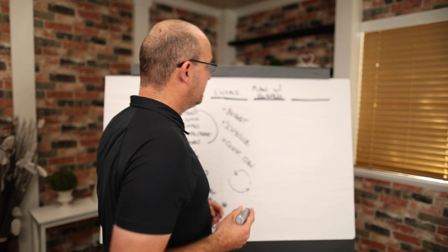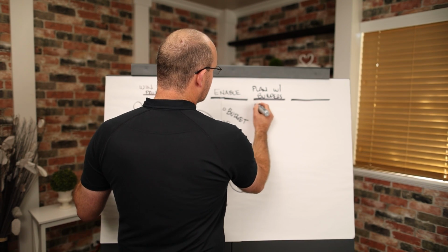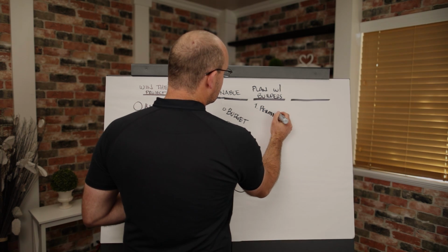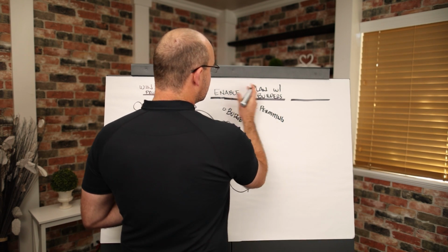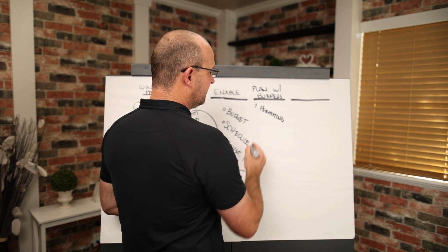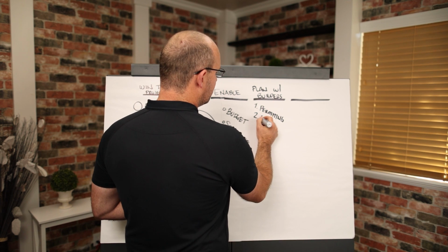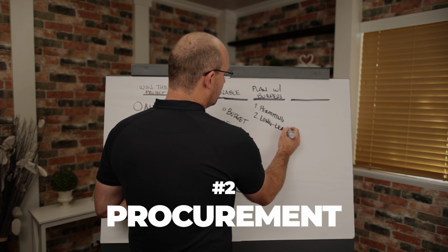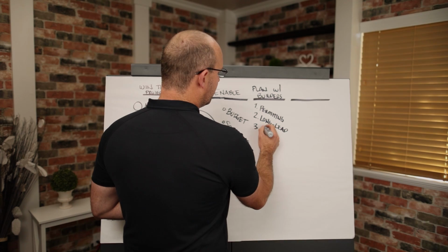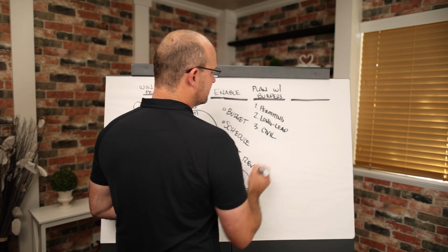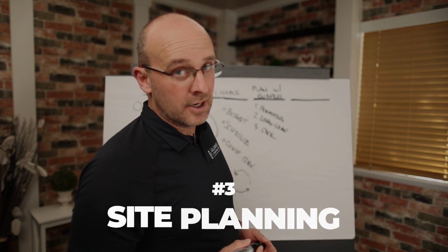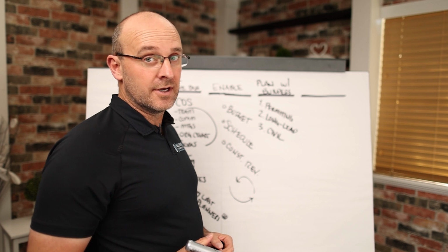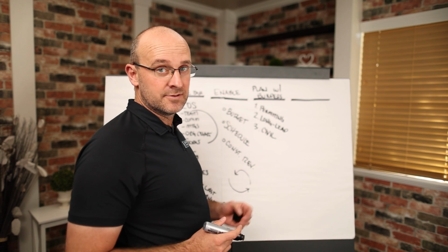So there's a couple of key things that we'll do in this phase. We will really lock down permitting, okay? And this right here can be in the design development CD phase. We are really going to make sure that our long lead procurement is well underway. We're going to make sure that any civil considerations like preparation according to the soils report or any relocation of underground utilities is done in this phase of pre-construction.